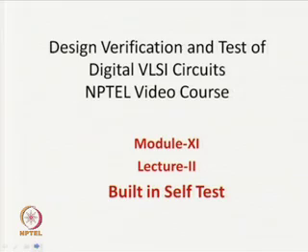Okay, so welcome to lecture 2 of module 11 in testing. So, built-in self-test. In the last lecture we were looking at the assumption that whatever test patterns or testing we were discussing at length were for offline testing. So, what do we mean by offline testing? That is, the circuit has been fabricated and put in the ATE, and we are applying test patterns to test it.